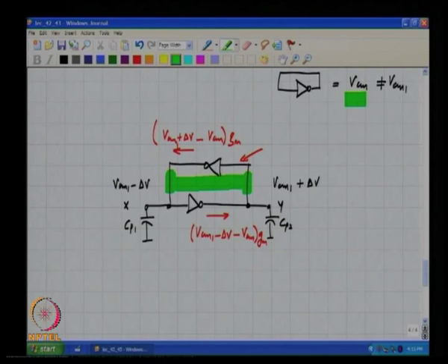I mean, this common mode analysis only makes sense when things are linear, right. In the very beginning of the regeneration phase, we hope that things are still linear because the input is very small and we are just looking at around the time when the phase phi 2 goes high, right. So, as far as common mode signals are concerned, the common mode impedance at nodes x and y is a very small number, right.